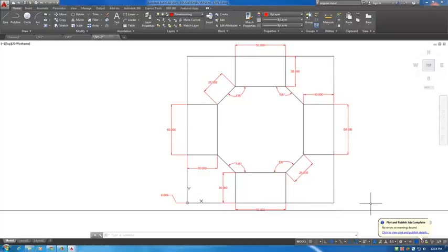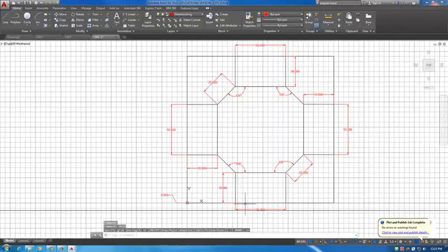So when we talk about coordinate systems, basically you're talking about a Cartesian coordinate system, your x, y's, and z's. X being the horizontal axis, y being the vertical axis in AutoCAD. Everything works off that coordinate system. If we turn on our grid, that is a coordinate system. Every line on here, every square is a specific coordinate or a unit. So we can use those units to specify points.